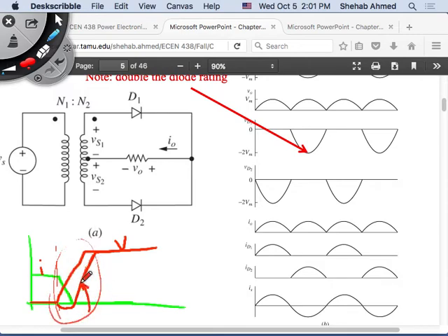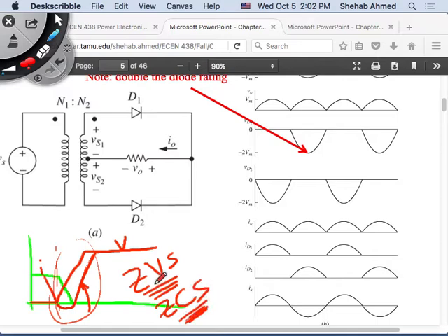And there are some circuits that instead of working on the voltage, they work on the current. So they keep the voltage as it is and try to bring down the current waveform before the voltage waveform rises. Right? So their objective is the same. The objective is to eliminate switching losses. And there's a whole family of converters called zero voltage switching converters and zero current switching converters. So some of them keep the voltage down to 0, and some of them keep the current at 0 while the voltage rises. You either do this or that.